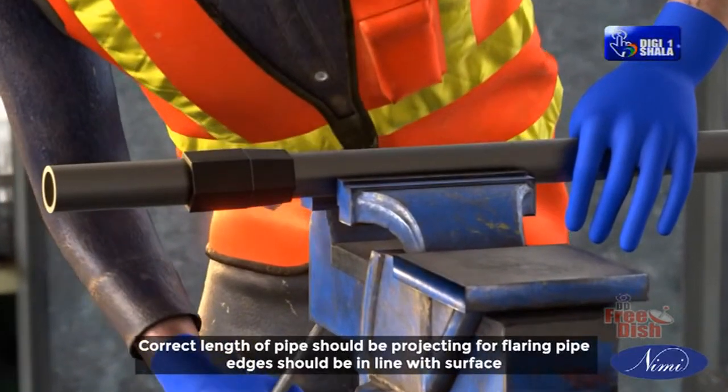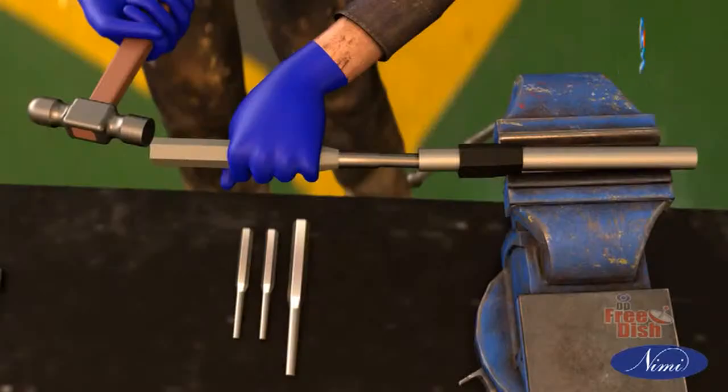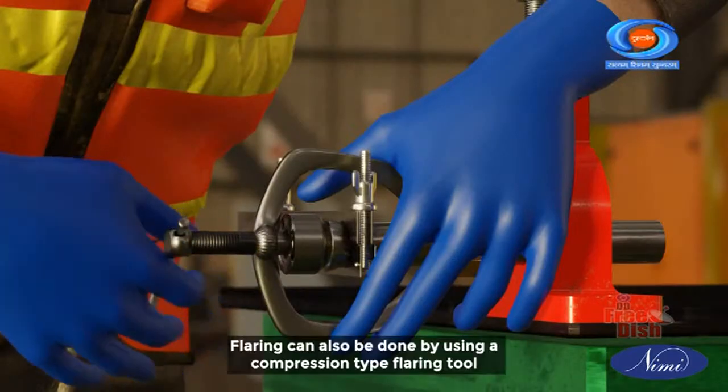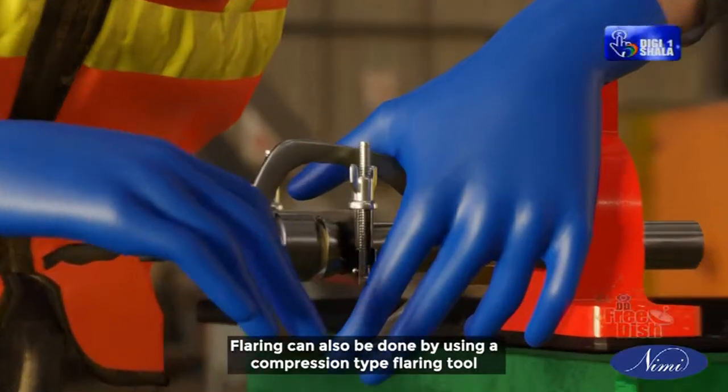The correct length of pipe should be projecting for flaring; pipe edges should be in line with the surface. Using the flaring punch, flare the pipe end. Flaring can also be done by using a compression type flaring tool.